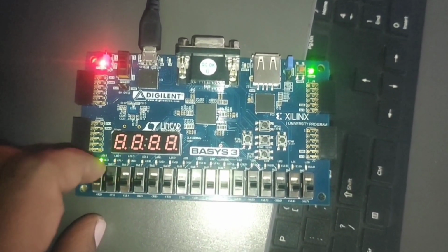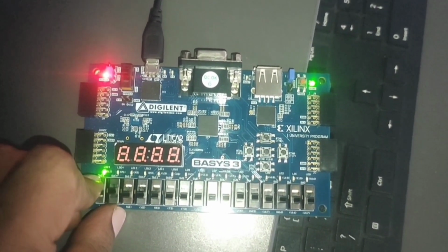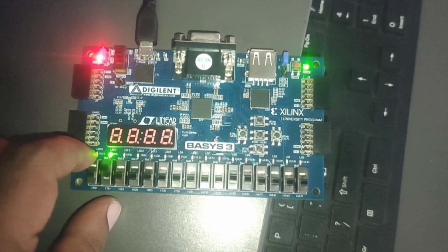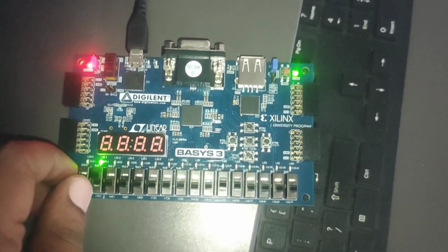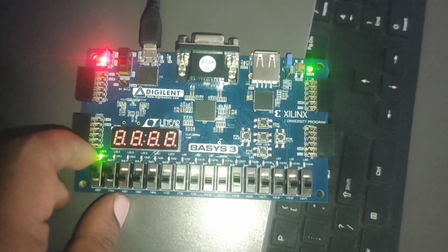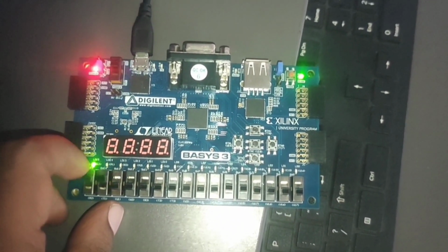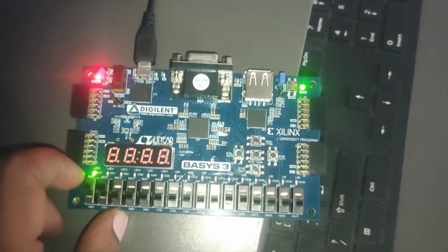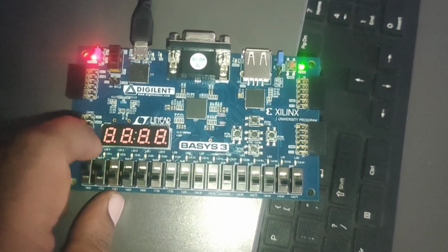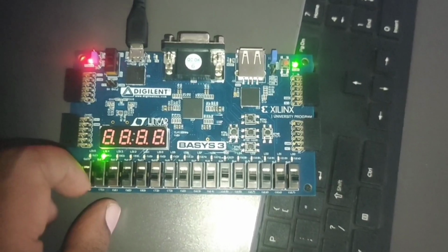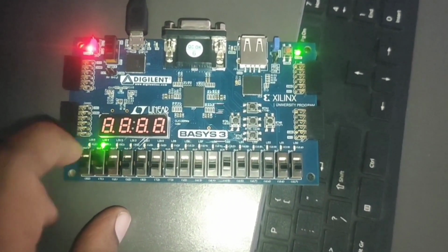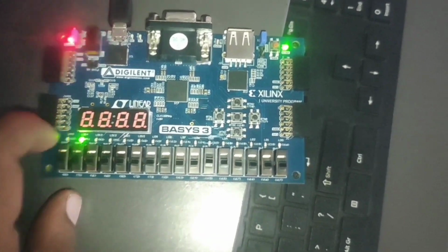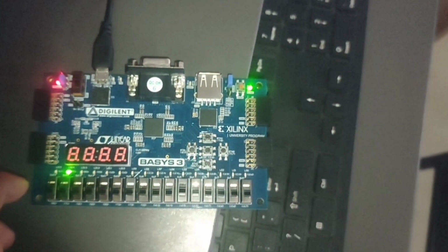And next I'm going to make SR to 0 1. So the output goes to 0, Q goes to 0 and Q bar goes to 1. So if I make it 1 1, it will be an unknown state, right? Uncertainty, right? So next, if I change it to 0 1, output becomes 0 1, right? So if it is 0 0, it will be in the no change state, right?